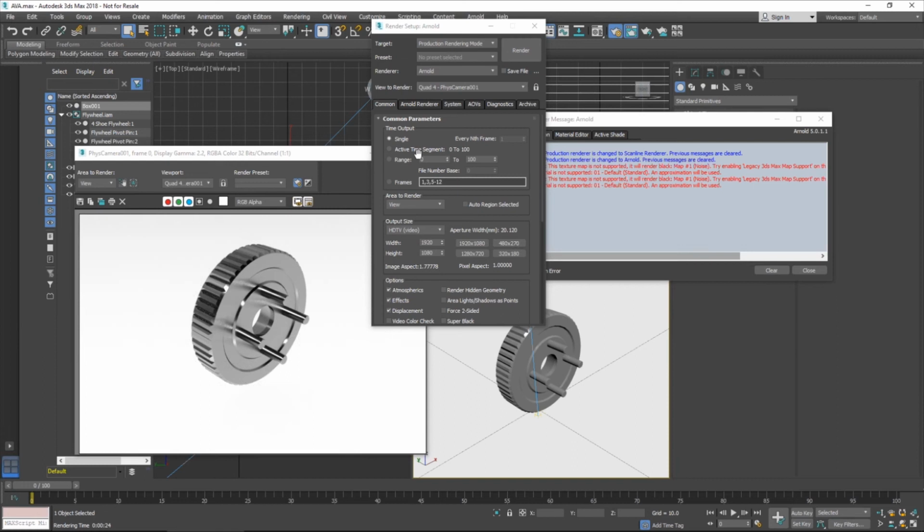Exactly, and that's how Inventor does it in the background, right? So if you're looking at Inventor and you want to generate an animation, say for example for a simulation, which is one thing you can do in Inventor, what it does is it creates all of those frames. So you've got 50 of them. It's going to generate 50 individual frames and stitch it for you. So if it fails anywhere during that 50, if you actually look in the output file location, there will be like 45 images there because Inventor hasn't actually stitched those together yet. So that's just one thing to note.